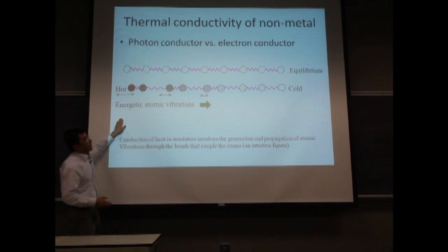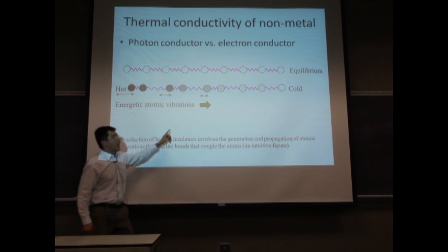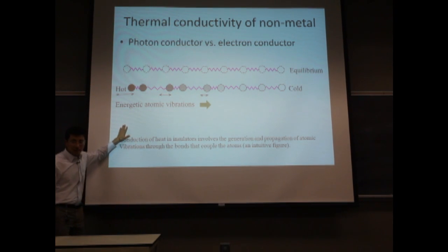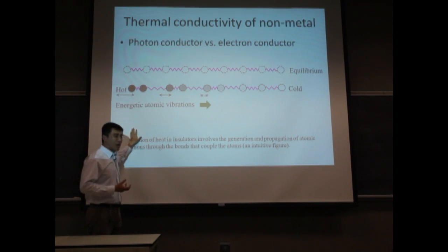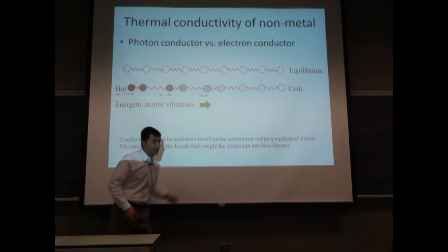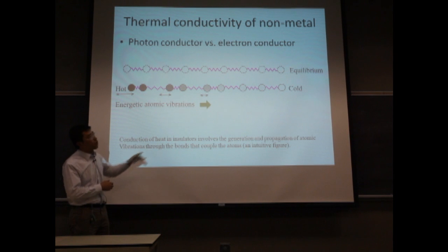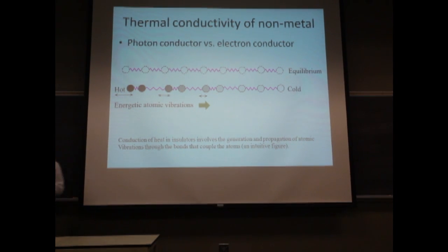So if you heat the material from one end, at the hot end the lattice vibration becomes severe, and the number of phonons increases. And the phonons, as quasi-particles, diffuse across the entire material to the cold end, which transfers the heat. That's the thermal conductivity in a non-metal.